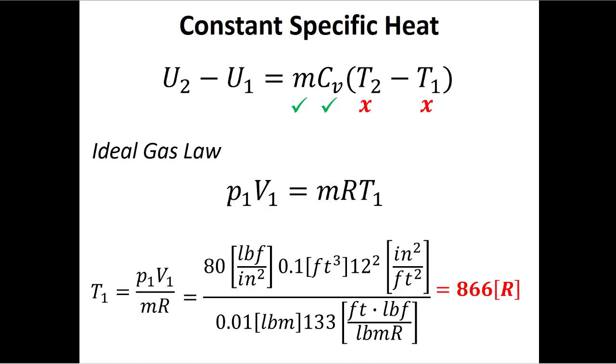Now it's important to realize that because there's no delta T in this equation, this equation will always, every time, give me a temperature in degrees Rankine. Or if I'm using it in metric units, it will give me an answer in degrees Kelvin. So whenever I have an equation where the temperature stands alone and it's not a change in temperature, I either want to put in an absolute temperature or I'll get out an absolute temperature. And absolute temperature scales have absolute zero as 0.